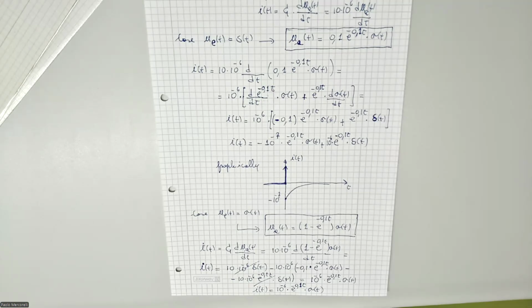This was my original reason why I dedicated a block on this. Because in control, it's important to understand what happens between 0 minus and 0 plus. Because look, we have an impulsive current. And this in control is important to understand because the impulsive current is destructive. Theoretically, we have infinite amplitude. This means everything is destroyed from the control. We fail in this case.